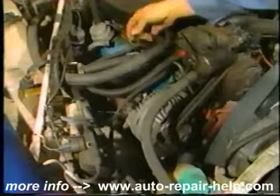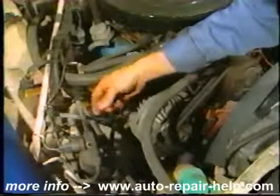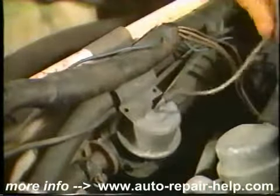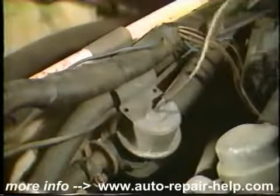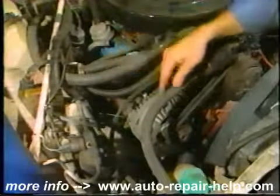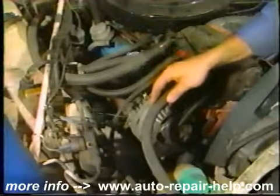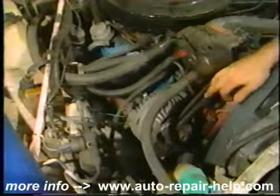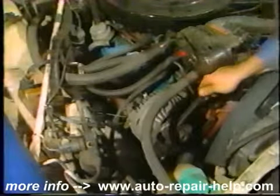Inspect the heating and air conditioning electrical wiring. Look for loose or defective vacuum hoses. Ensure that the air conditioning hoses are properly routed and inspect for refrigerant oil leaks. A slipping or defective drive belt is also a common problem.